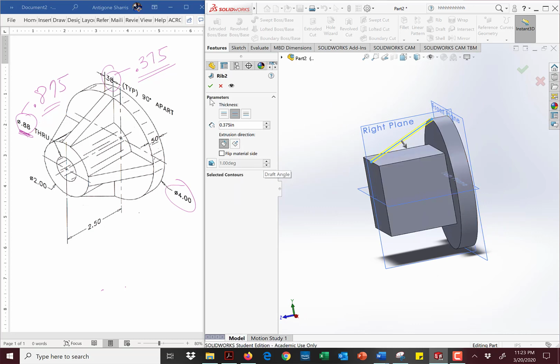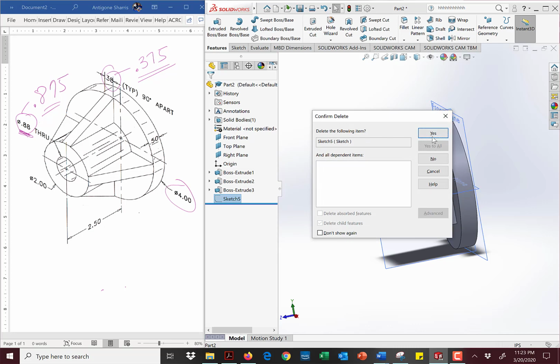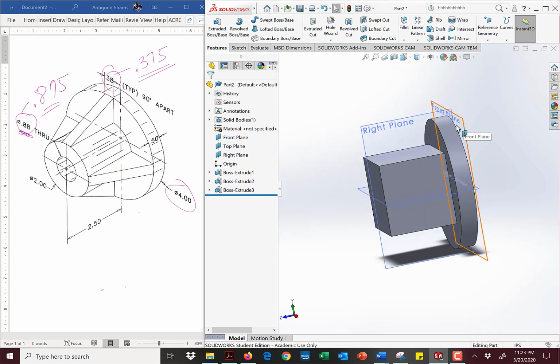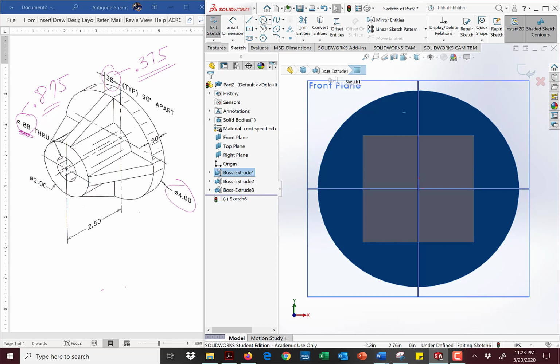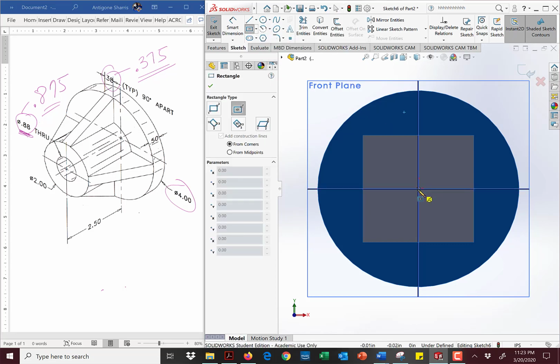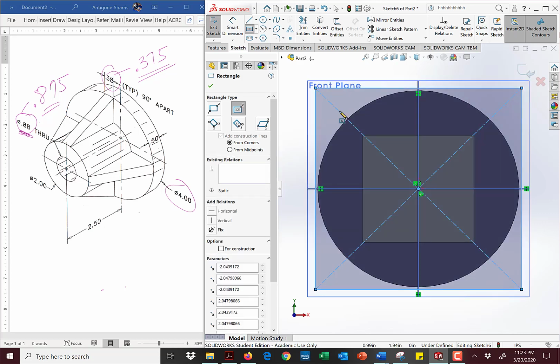So then what's the issue? Well, the front is now square, but what's the back? Back is still a round shape, so it's not going to work. Period. So, one more time, I'm going to go ahead and pick this face. I'm going to create a new sketch on that face. Pick normal to, and I'm going to make a big square off this center. Go out to this object. Okay, there we go.